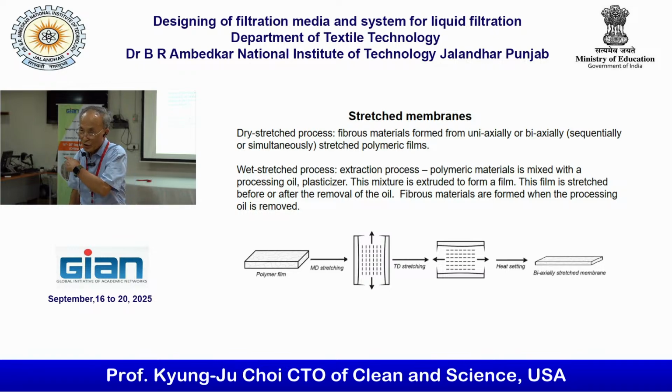That's why they use the wet stretch. They use some sort of solvent to make their paste. That's the difference. But EPTFE is made that way. So the wet stretch process is making expanded polytetrafluoroethylene film.